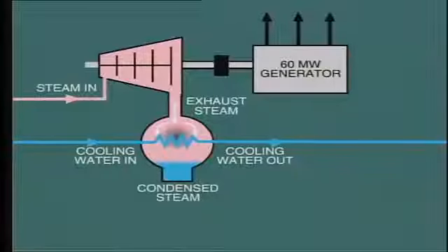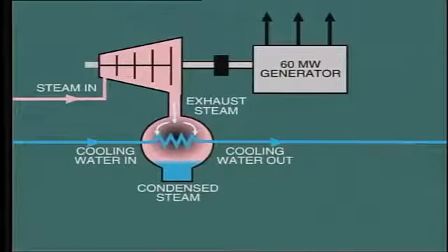The dramatic change in volume from steam to water leaves a large empty space, and as the condenser is a closed vessel, the result is a vacuum. The actual pressure in the steam space of the condenser and correspondingly at the turbine exhaust will be about 1 to 2 psia, depending on actual local conditions.